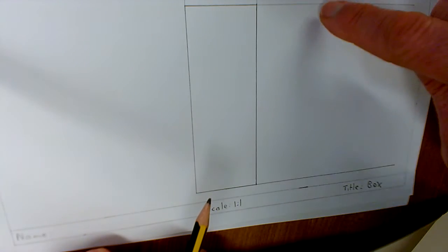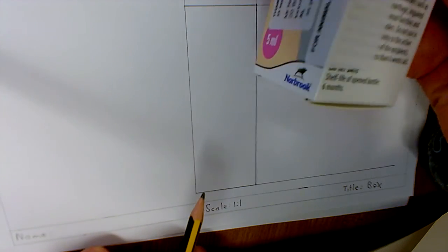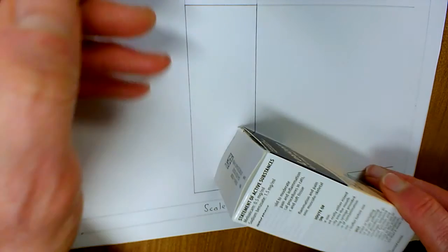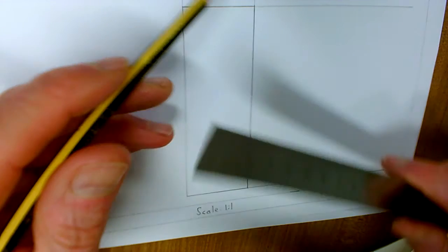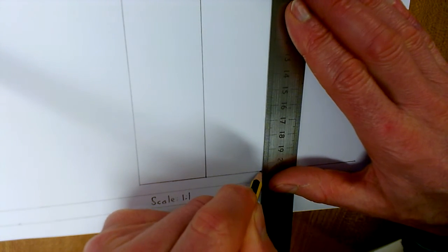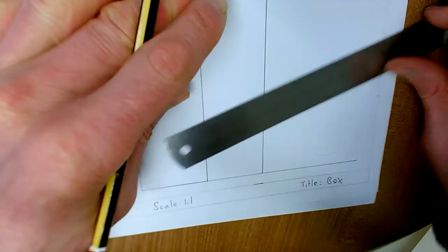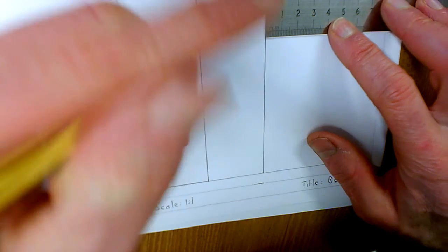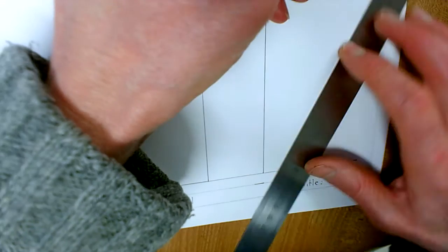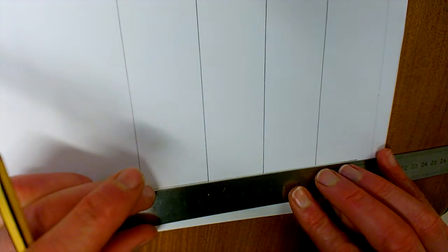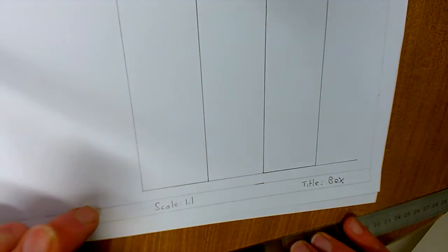Okay, so again, I've got my top. Now I'm drawing that view. The depth, remember, is this distance here, and the depth up here was 40 millimeters. So I'm going to bring my drawing across to here, so that's going to be the edge of my box, and then I'm going to measure 40 millimeters for my depth, because obviously this is a side view, like so. And again, take it down like that, and across like that.